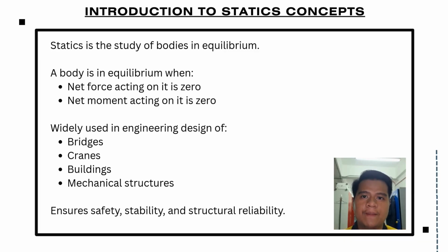Okay, the next part is the introduction to engineering statics. Firstly, engineering statics is a branch of mechanics that deals with bodies in equilibrium, meaning that the body is either at rest or moving with a constant velocity. In equilibrium, the sum of all forces and the sum of all moments acting on a body must be zero.